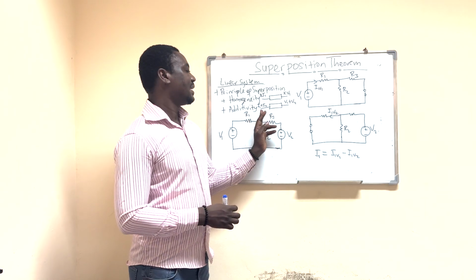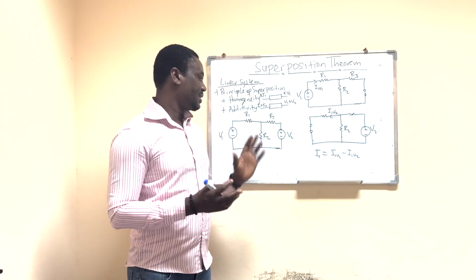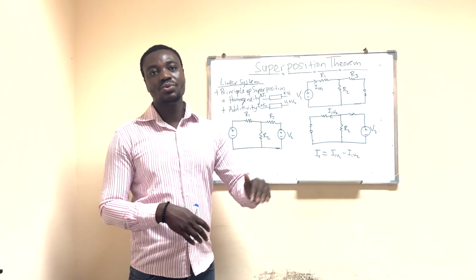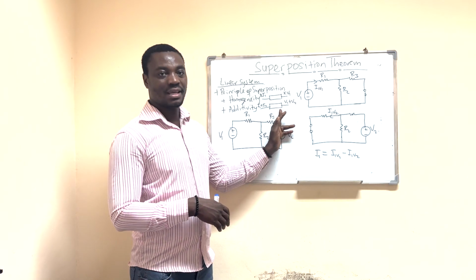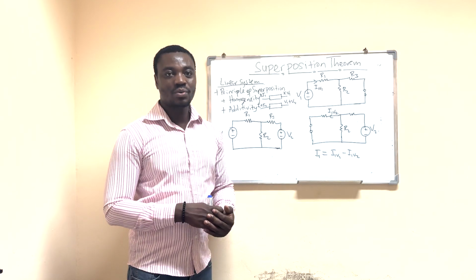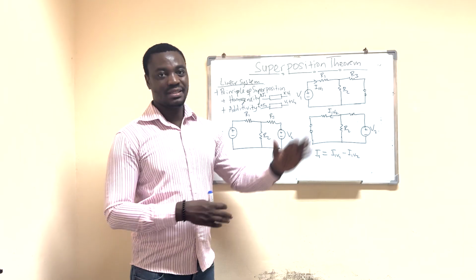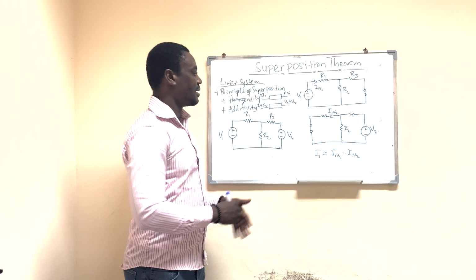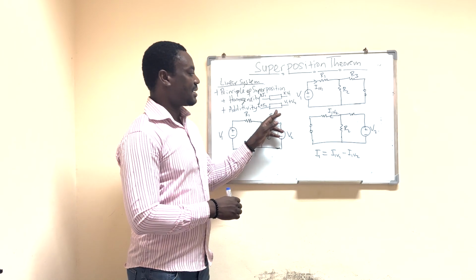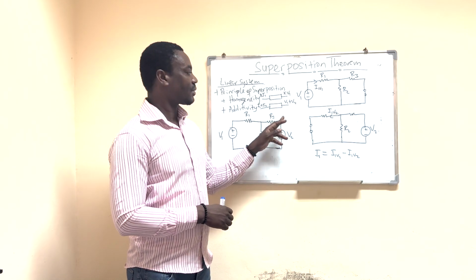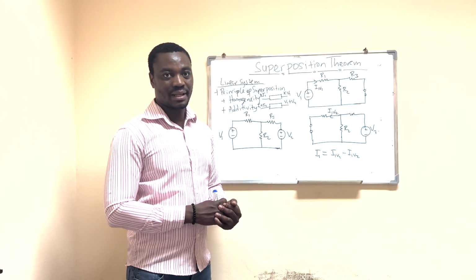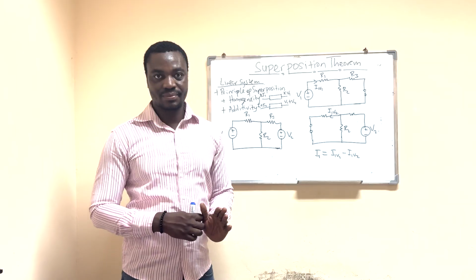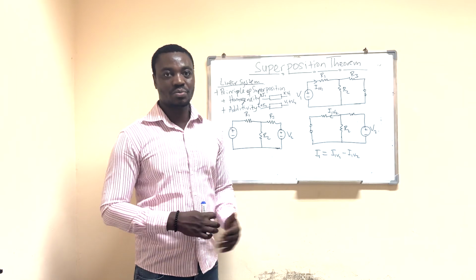And then when it comes to additivity property, again, we are dealing with the resistor as a system. As the name implies, additivity, we are talking about addition, right? The sum of current into our system, which is a resistor, is equal to what? Also, the output here, we have the sum of what? Output, right? So the resistors that you can find in the circuit diagrams that we normally have, they are all linear systems, right? Because they all obey the principle of superposition.